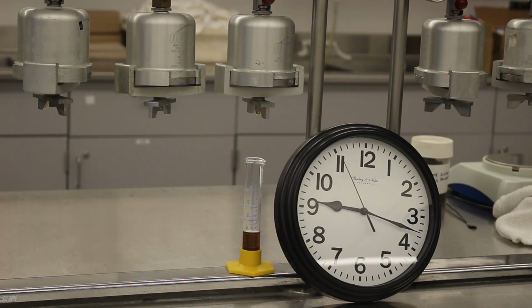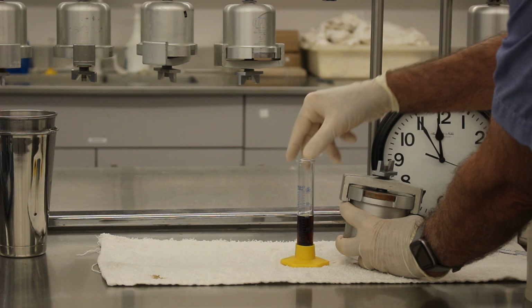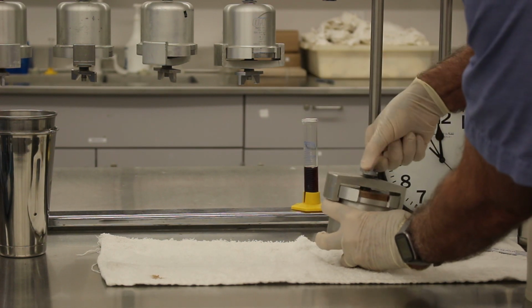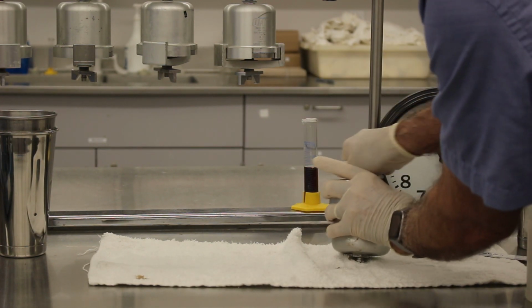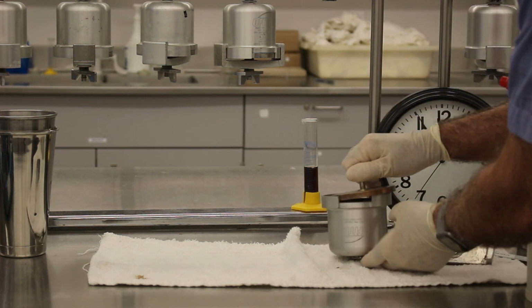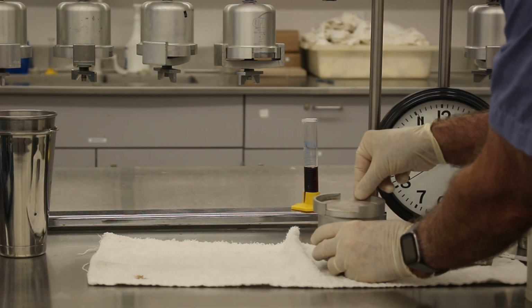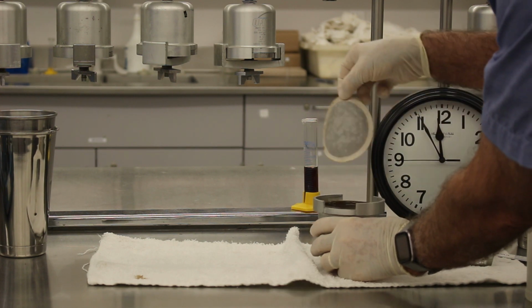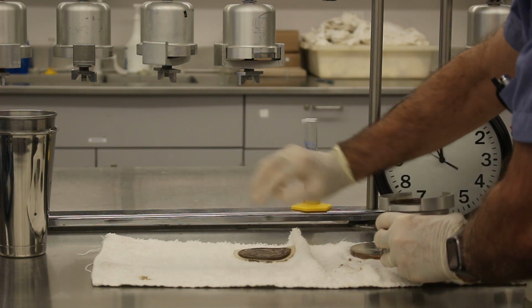Report the volume of filtrate in milliliters as the API filtrate report. Round your answer to 0.1 milliliter. Report at the start of the test the mud temperature in degrees Fahrenheit. At the end of 30 minutes, remove the cell from the frame, first making certain that all pressure has been relieved. Then disassemble the cell, discard the mud, and use extreme care to save the filter paper with a minimum of disturbance to the cake.